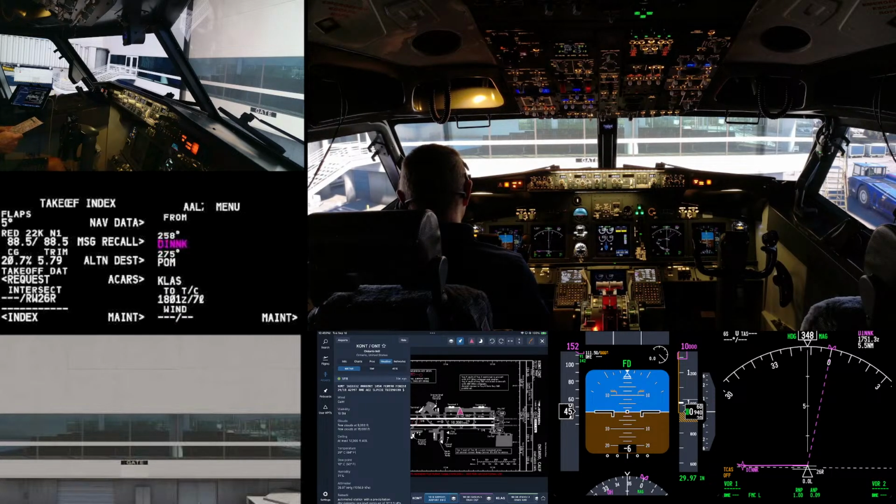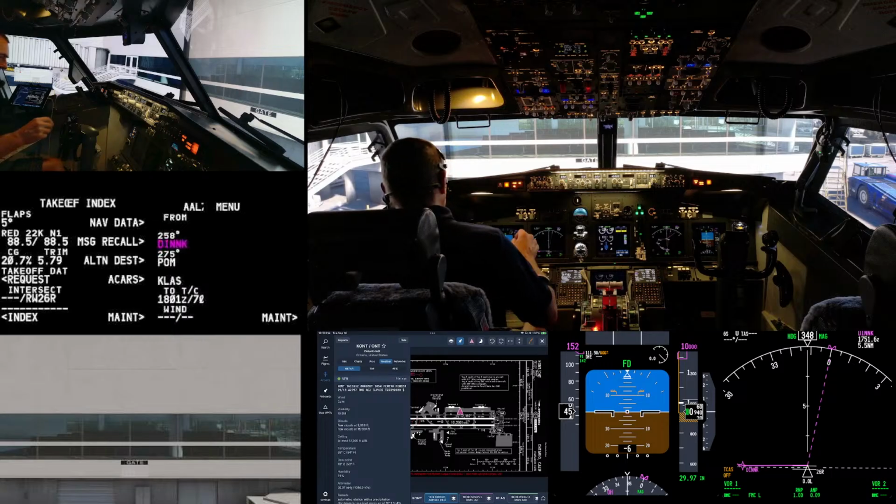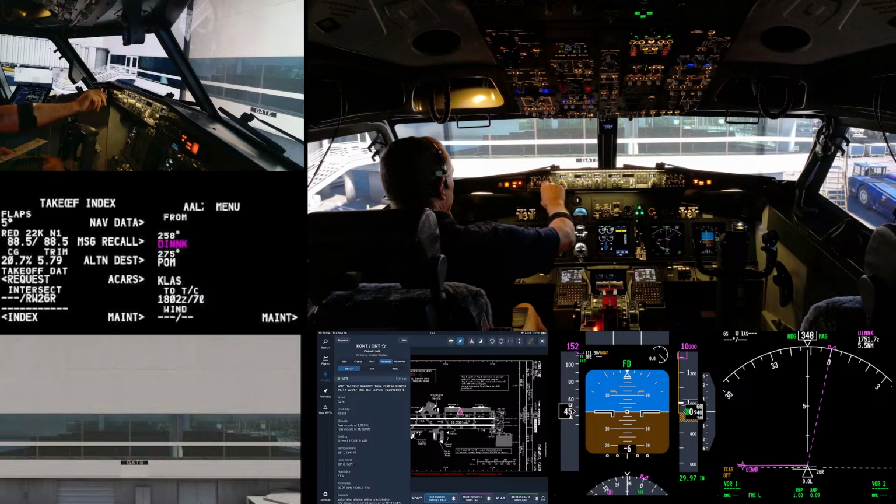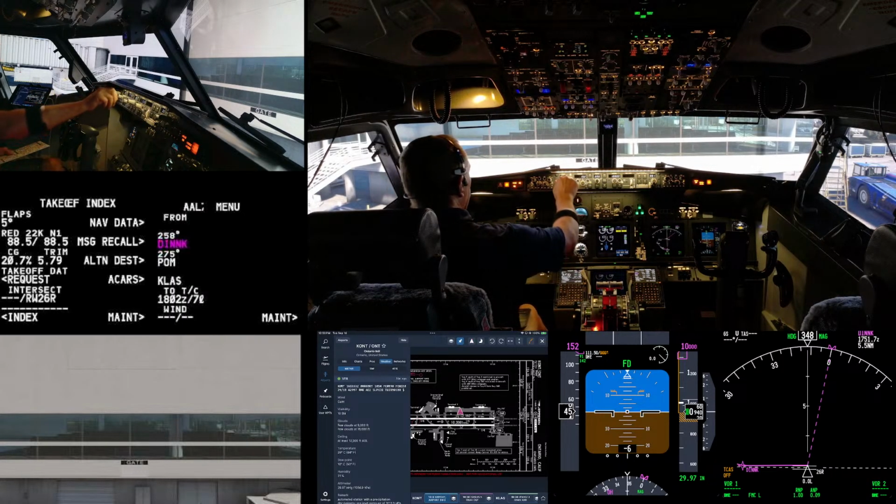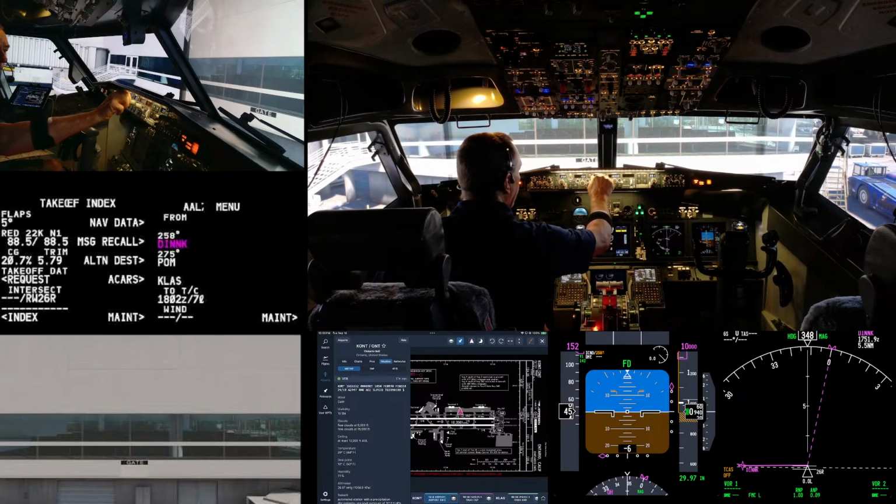Alright, so that's PFD is checked. Artificial horizon 45 on the speed tape, check. V1 speed shown. Confirmed 142 and 152, check. Initial climb altitude shown of 10,000, checked. And heading indicator matches terrain. That's correct. Let's see. 258 is the heading on the outbound course. 258. So we have then course 1, 258.